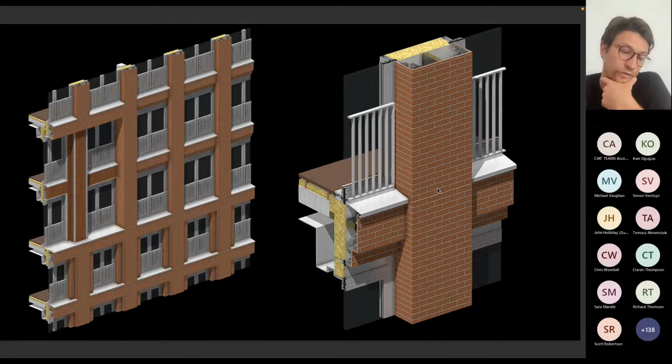It requires scaffold for masonry, and for brick slips it definitely requires at least a mast climber to install it. So for the high rises with the brick finish, it is recommended to use unitized rain screen brick slips assembly, similar to what you see here.